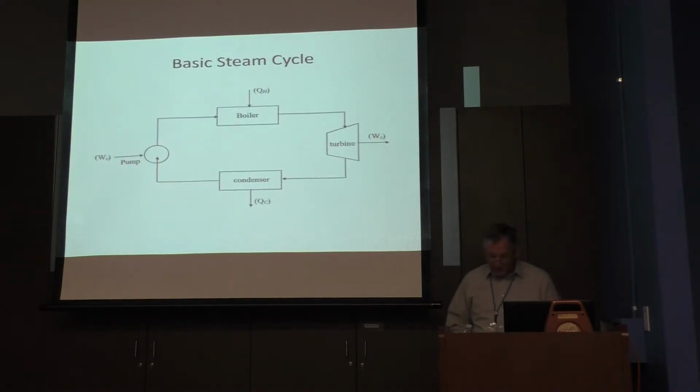And here's what I mean by a basic steam cycle power plant. Here what happens is you use a boiler to create high pressure, high temperature steam, which is used to drive a steam turbine that also then can drive either industrial machinery or an electrical generator to produce electricity. And the low temperature, low pressure steam from the turbine exhaust is condensed back to water in a condenser, which is then pumped back into the boiler to start the cycle all over again.